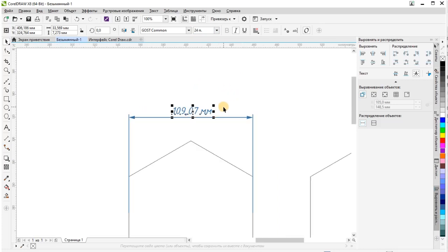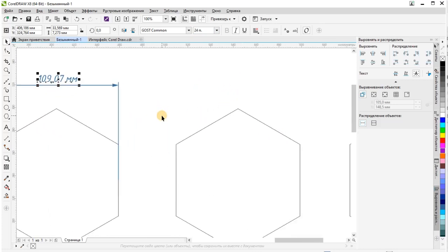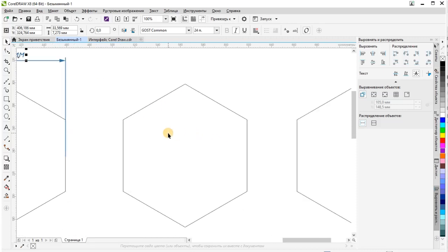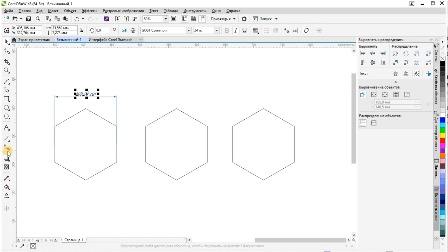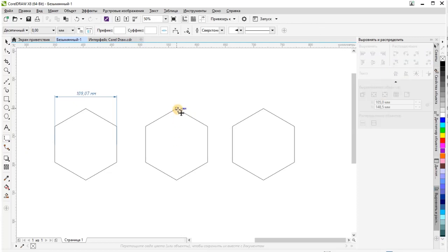Segment dimension lines measure the linear distance between the end nodes of a segment or the linear distance between the 2 most distant nodes in multiple segments. Segment dimension lines can also measure selected successive segments.